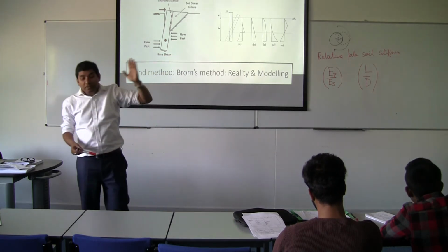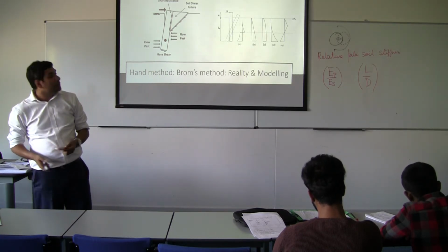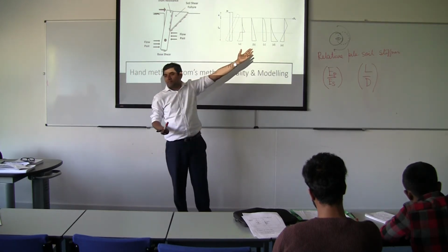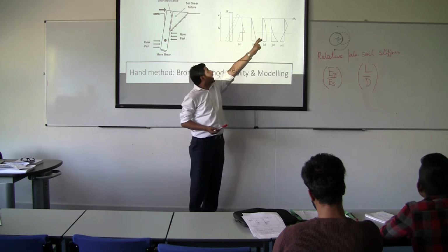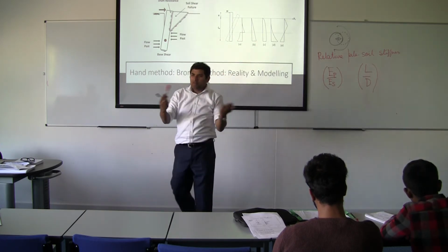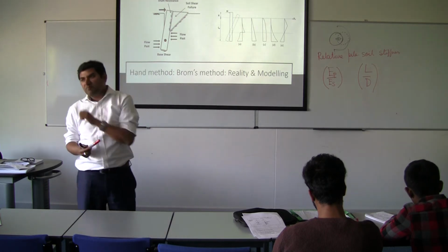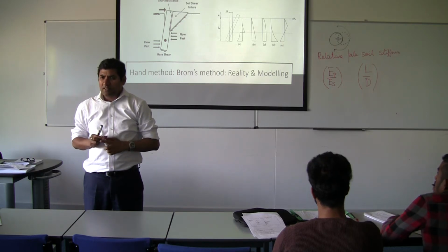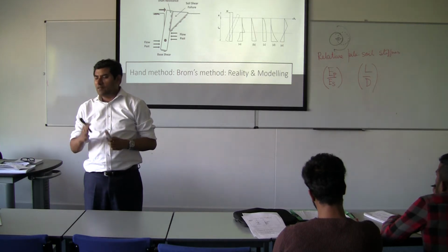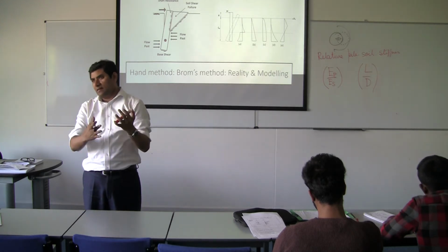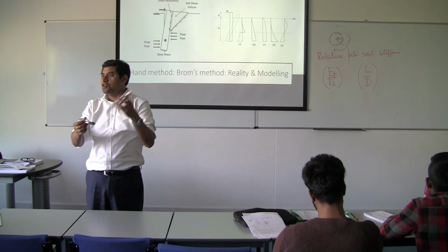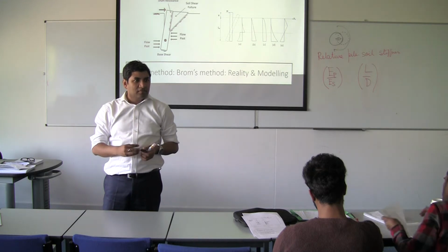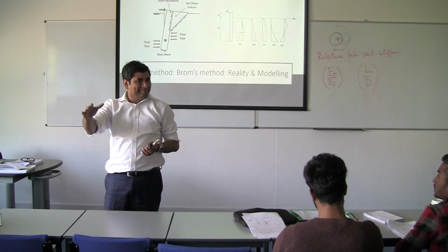So if you see, to do this sort of calculation, what you do, you can assume a pressure distribution. So you know the applied force and you know the pressure distribution. You assume something, and from there you can work out the maximum moment. Yeah, I think you've done it, sir. You've done it in Blum's method. Yeah, so you have a shear, like a sheet pile design, similar thing. You assume a pressure distribution, and then you work out the shear force zero. Shear force zero is maximum moment, and you can work out the moments. Yeah, so you assume a pressure distribution.